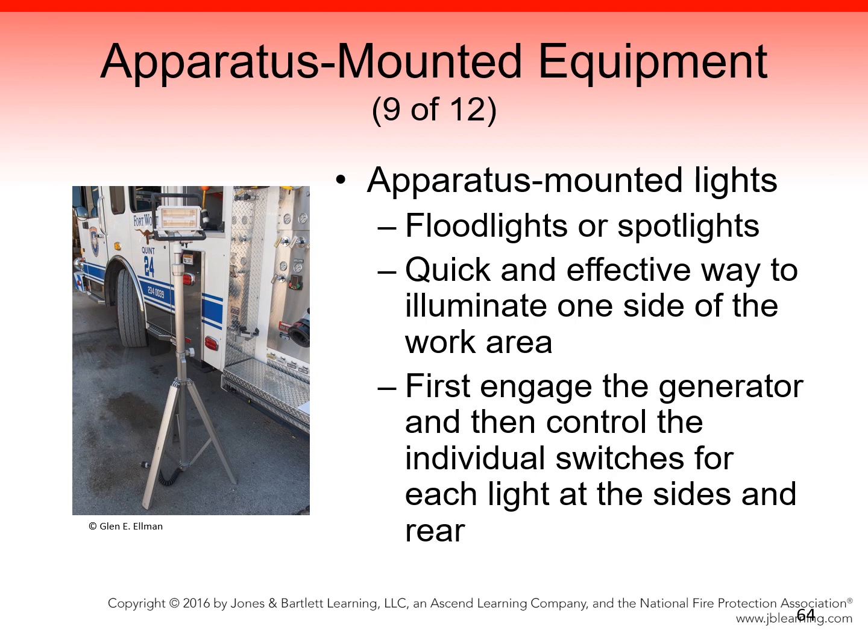Do not preset all of the individual light switches to the on position. Turning on all of them simultaneously may place an unnecessary load on the generator and seriously damage it. Some lights may be angled slightly toward the ground to provide better coverage of the emergency scene. Other types of lights are attached to a pole and elevated from different locations on the apparatus. Figure 11-27. These lights may be manually raised from their nested position to better illuminate the emergency scene. Many newer apparatus use LED scene lights that run off the vehicle's 12-volt system and do not require generator power.